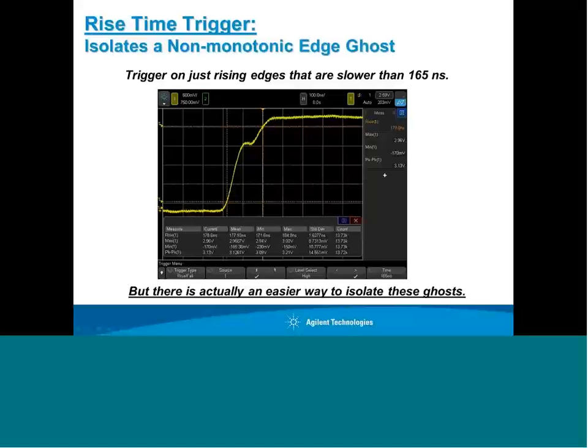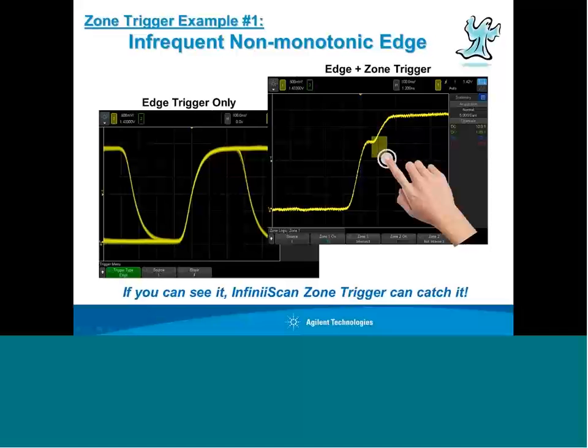Once you've been able to do that, you've isolated the problem signal, now you can use other channels of the scope to perhaps probe other signals that may be interfering with this signal, maybe synchronous to it. Maybe there's a power surge or something else that's happening in the system that is happening synchronous to the problem signal. But there's actually an easier way.